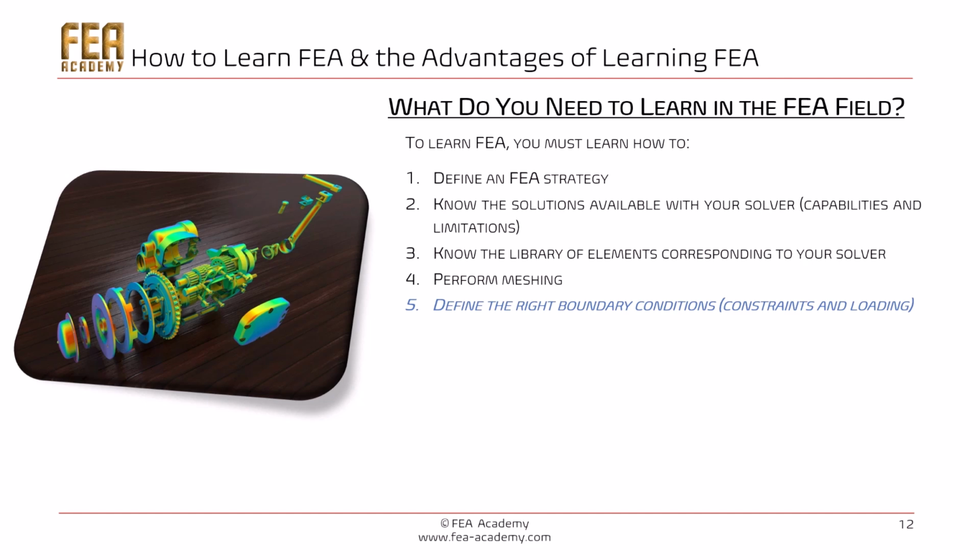But keep in mind that the FEA solver will give you a solution in most of the cases, even if you choose the wrong boundary conditions. So defining the correct boundary conditions ensures that you submit the right set of equations to the solver. I mean the equations which correspond to the reality.